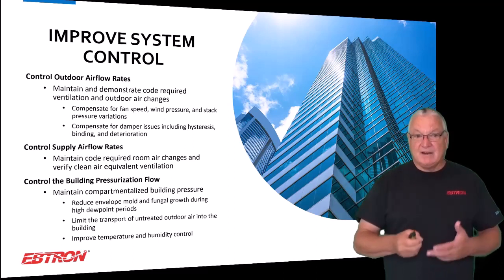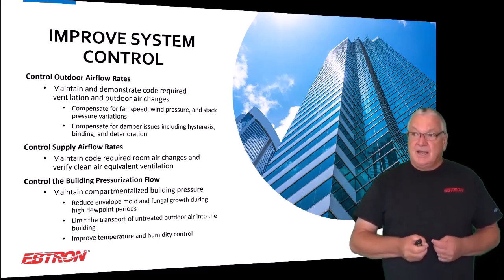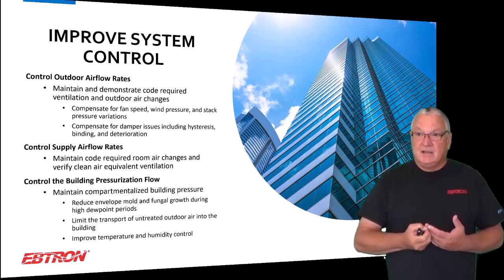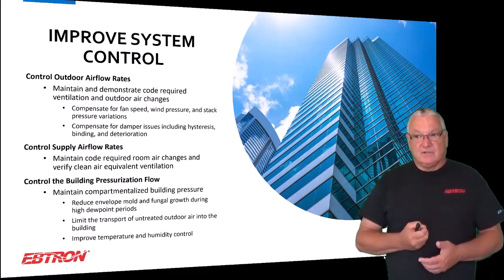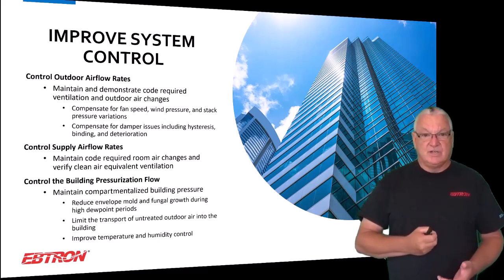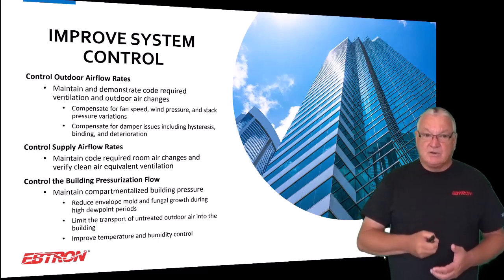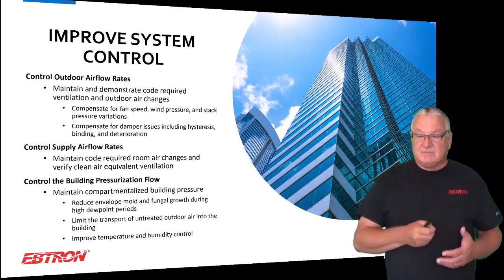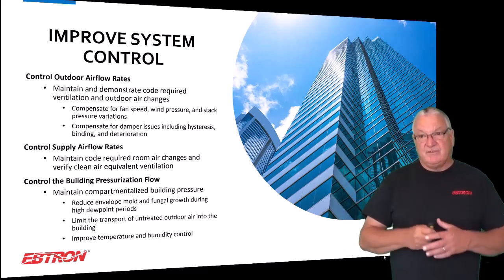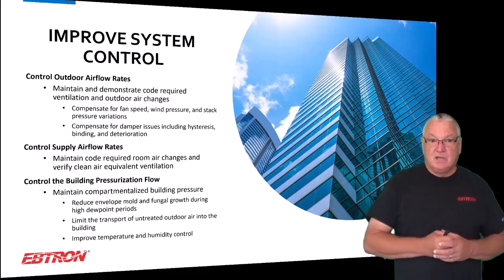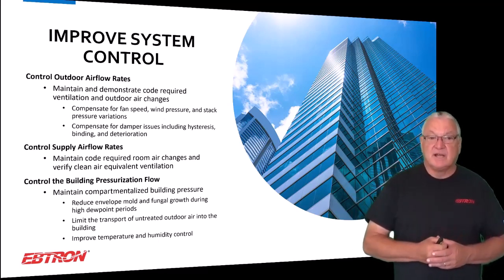So clean air equivalent ventilation. If I was to do a presentation on that right now, we'd see that we have outdoor air for dilution, but we also have the potential for clean air for dilution that's recirculated. So it's not just now measuring and controlling outdoor airflow rates, it's measuring and monitoring and verifying supply airflow rates when people are making claims of using clean air equivalents, okay?